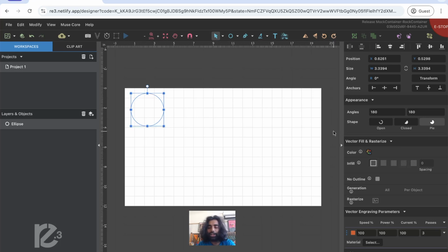First, we want to actually create a fill in our vector. That's the whole point of this, right? We want to have a shape that has a fill. So, if I go to the infill tool, there's a series of different types of infills I can produce. It actually doesn't really matter which one you use, as long as your spacing is 0. If it's not 0, then it'll change the look on the final output, but most of the time it'll be 0. So I always just use horizontal lines. And now I have a filled in vector.